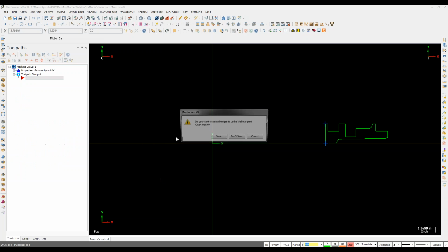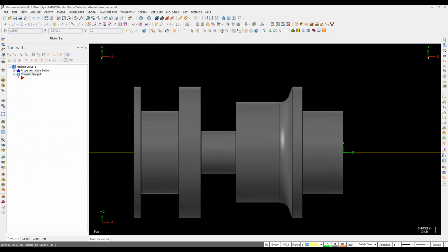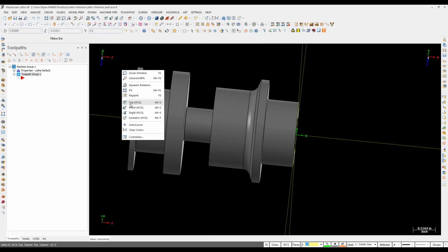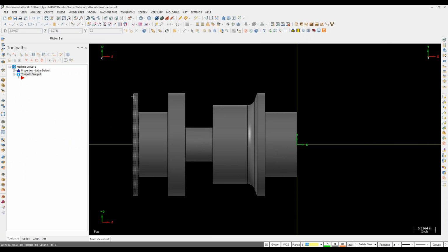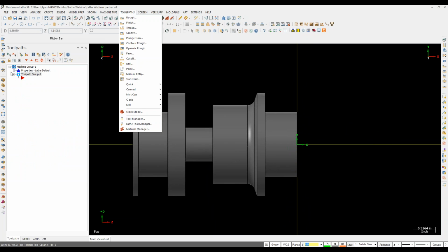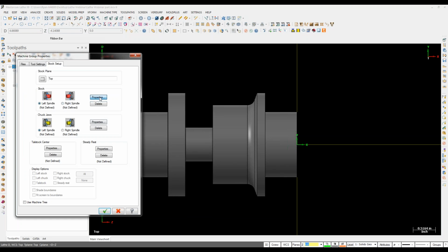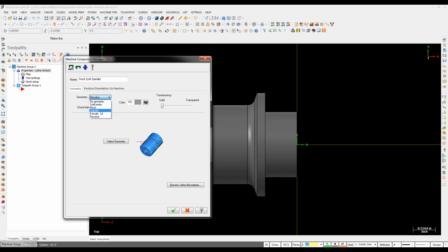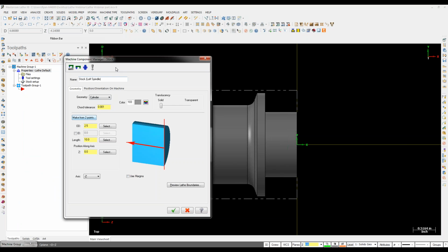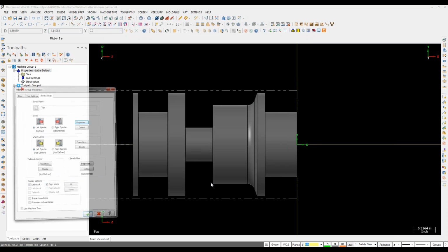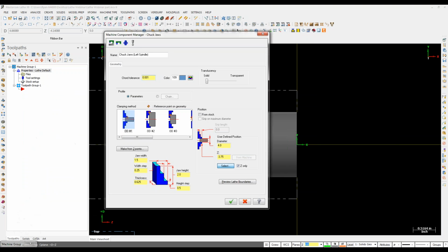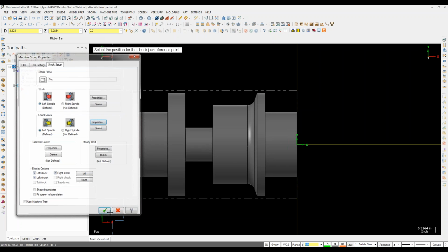And actually I should have a step file I can open up. So let's say this is my part again, and let's say I just want to kind of do some basic operations without creating that turn profile. So this is more or less along the lines of the solids chaining. So with this, if I want to, I can set up some stock, and we'll just set up some arbitrary numbers here. Cylinder, 2 inches, 10, that's fine. Again, jaws, always best to set those up. Let's say 4 inches. That way we can click and check against those if needed.